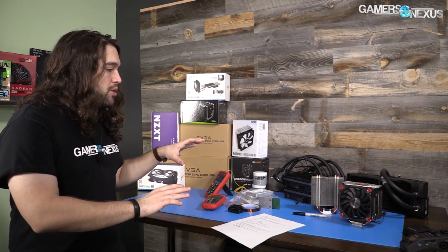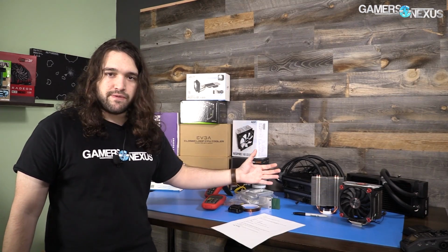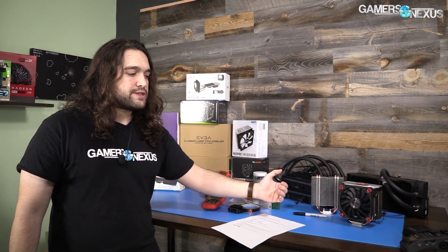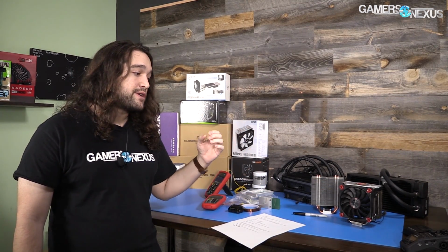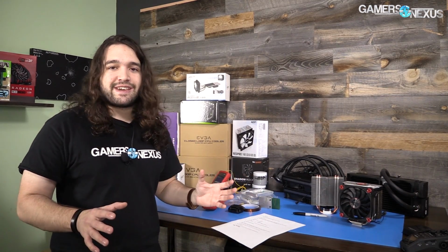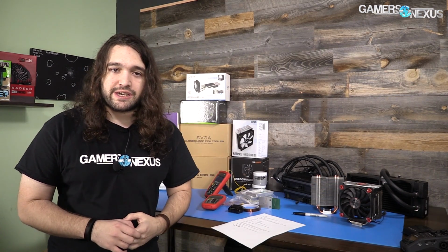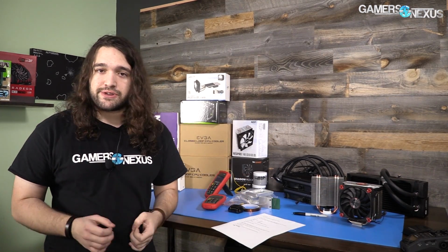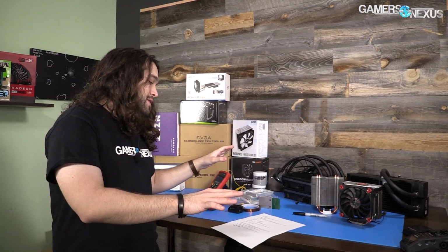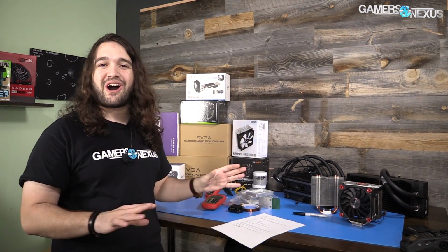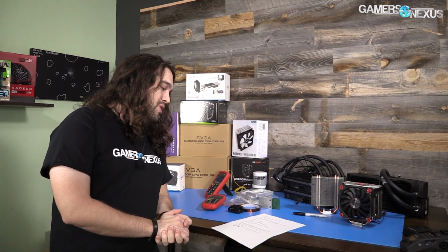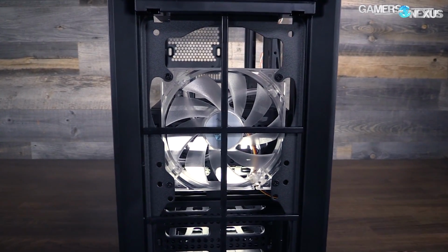Well, the reason is with thermal testing, we're not doing a CPU review. So you don't care about how does the CPU do these functions. All you care about is how do I make the CPU a steady state? How does it do one thing, generate heat, and do that one thing with exceptional accuracy and make it reproducible every single test? The answer is turn all of that power saving stuff, all the turbo boost and all that stuff off and fix vCore. That fixes most problems.